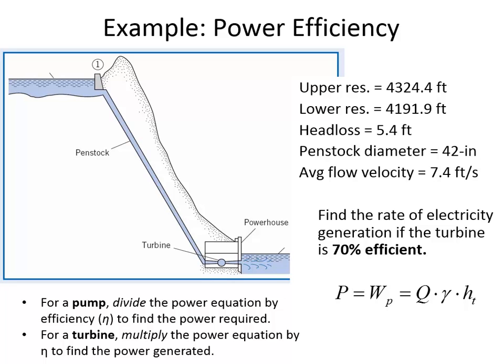Okay. Along with increasing Q directly, because if you make the area bigger, that's obviously going to change Q equals AV. Making the area bigger would also reduce the head loss, definitely. Remember, in the last lecture I said that next semester we're going to go deep with an equation called the Darcy-Weisbach equation. H sub F is F L V squared over D 2G. And so if you make the pipe bigger, D is in the denominator here, that's going to reduce the head loss. And so probably if we had, instead of a 42-inch pipe, a 100-inch pipe, then the head loss would be lower than that.